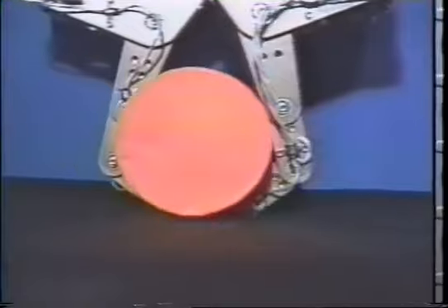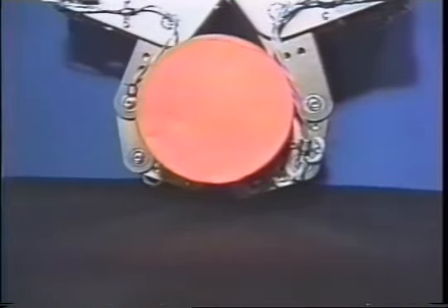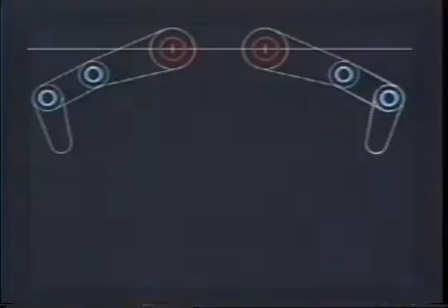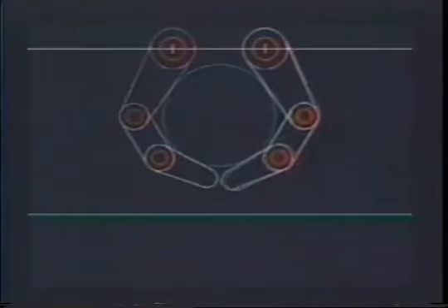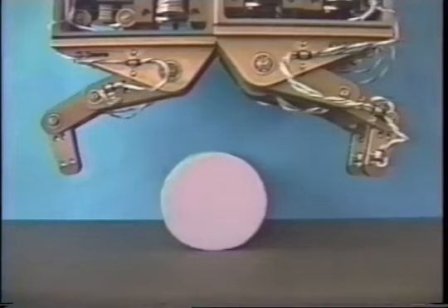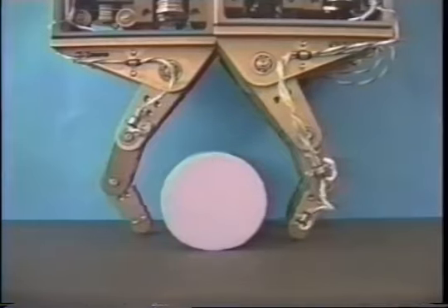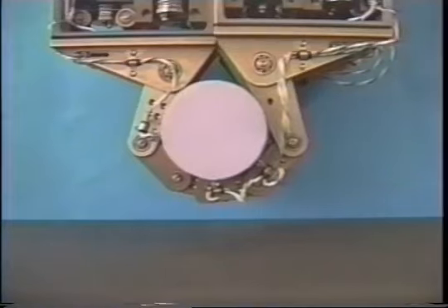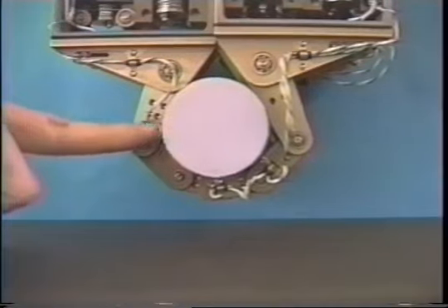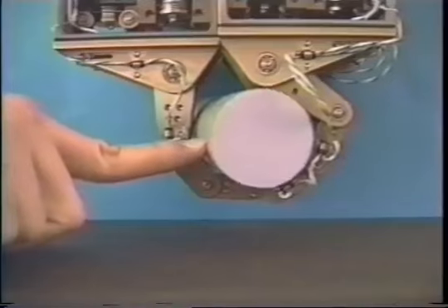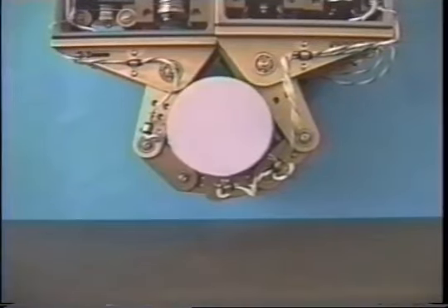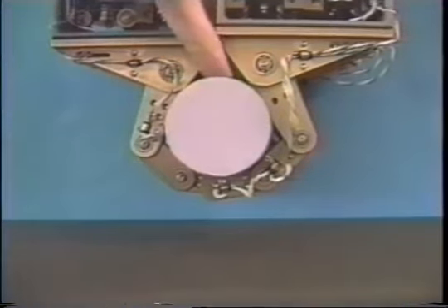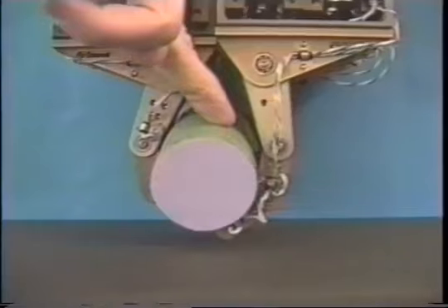The wedge effect-based enveloping grasp is first demonstrated. This procedure is explained by the wireframe model, where the red and the white joints denote the compliant and the position control joints respectively. Detecting the table and the object is done by utilizing a joint torque sensor. In the grasping phase, a constant torque command is sent to each joint. The grasp system behaves as if a virtual spring were connected.